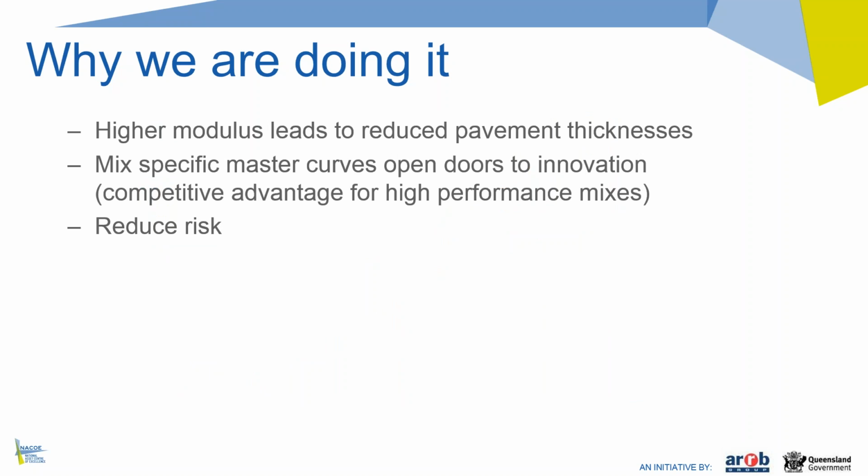Other reasons for doing it: these mix-specific master curves hopefully will open the doors to innovation, because it allows people who do mix designs to get the full benefit of creating mixes that have higher modulus values, especially if you combine that with higher fatigue values. So we're getting an actual competitive advantage of creating high performance mixes. In my opinion, we're also reducing risk at the same time because we're actually measuring the performance of these mixes over a range of temperature and load frequencies where we used to assume that. So this method should be more accurate and more precise in terms of characterizing the actual response of the material.